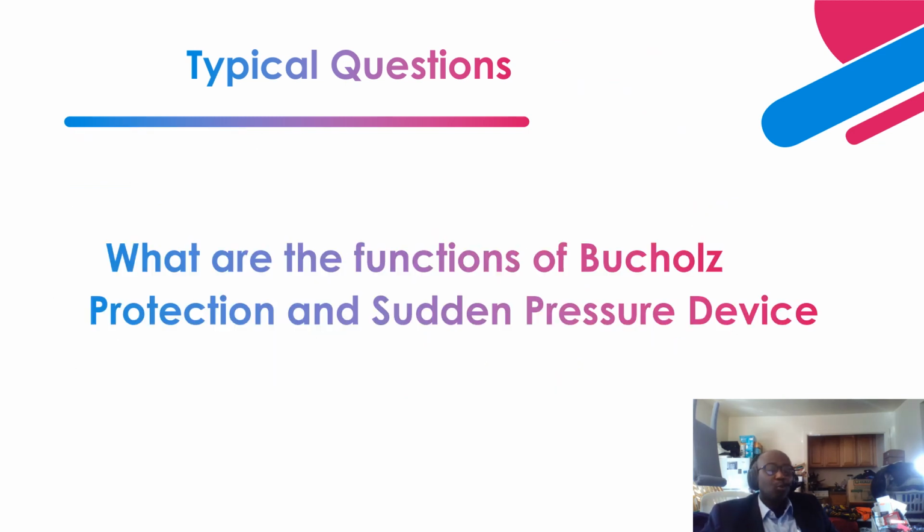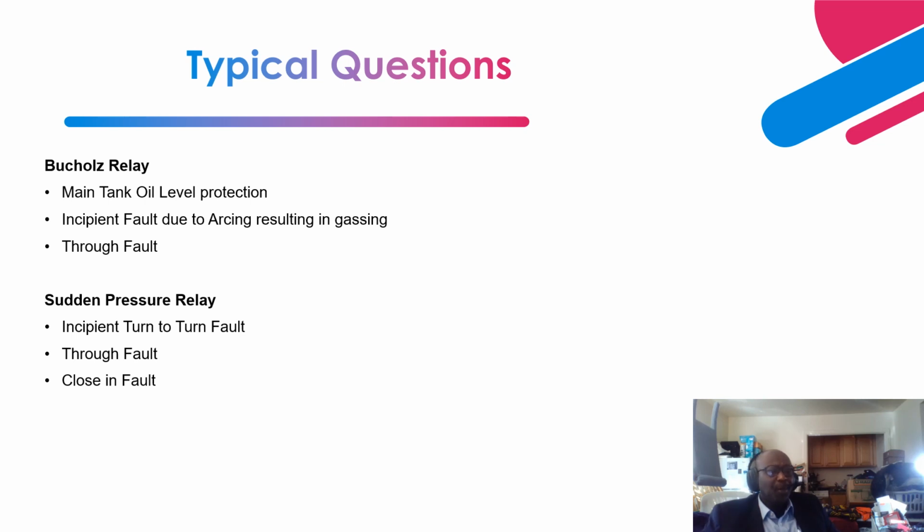Next question. What are the functions of the Buchholz protection and sudden pressure device? And this is how you answer that question. The Buchholz relay, and in the previous slide I showed you where the Buchholz relay is applied. Its application is in open conservator tank, free breathing transformers.